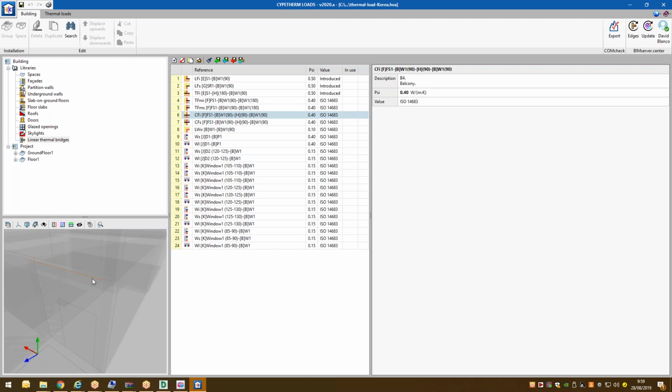We have control. Yes, what we are doing now is the previous step to the equipment selection or the system selection, for sizing the ducting or sizing the equipment for air conditioning or underfloor heating. We are doing the previous phase. It's analyzing the thermal loads. We need the peak load in order to select the equipment afterwards. So in this thermal analysis phase, we just were wondering if you analyze the thermal bridges. That was just the question.